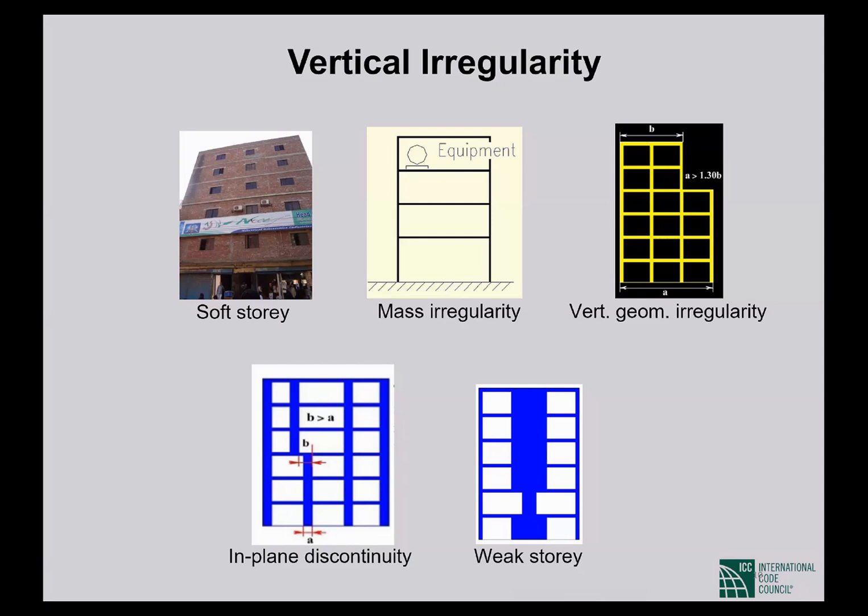So they may be broken quite easily, but it is difficult to deform them with a unit amount of force. That is the definition of stiffness. So if a story is devoid of any brick walls, whereas the adjacent stories have brick walls, then the story without the brick walls becomes a soft story.